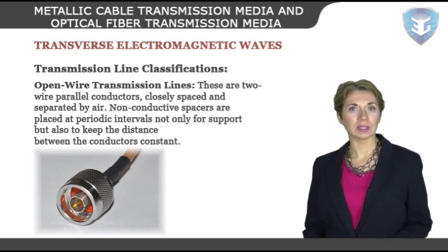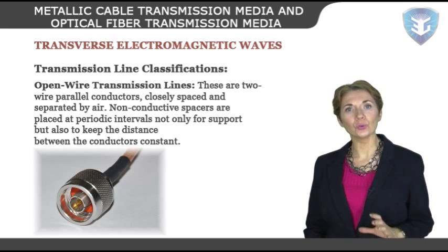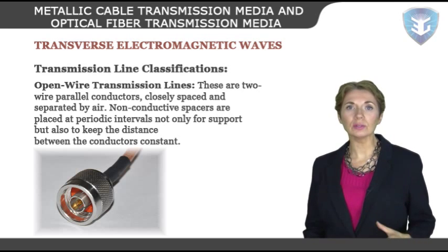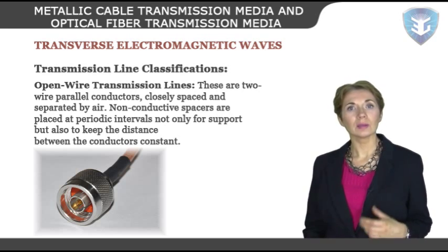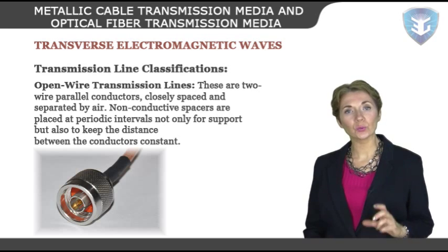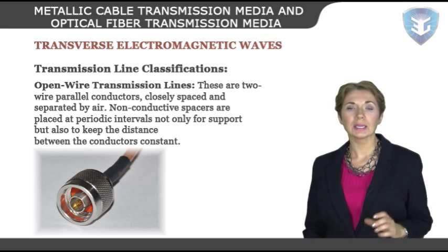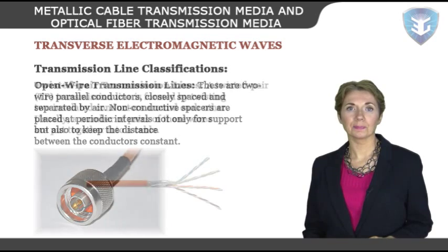Open wire transmission lines. These are two-wire parallel conductors, closely spaced and separated by air. Non-conductive spacers are placed at periodic intervals, not only for support, but also to keep the distance between the conductors constant. TEM wave propagates in the air between the conductors, which acts as dielectric.